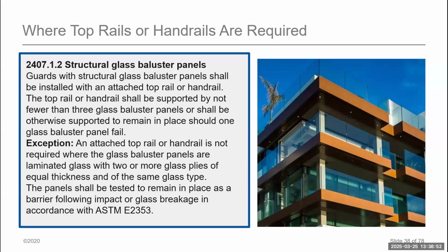We will also use this standard if we want to take the overall allowable deflection in the engineering of a system beyond 3/4 of an inch to an inch. We can sometimes get away with 2 inches plus in an overall guardrail if we have some testing that verifies it has taken its impact, the glass has deflected, the glass has come back, and it has returned intact, and it has not broken in any way. Then we can allow that standard to pass for a project and be incorporated into a project.